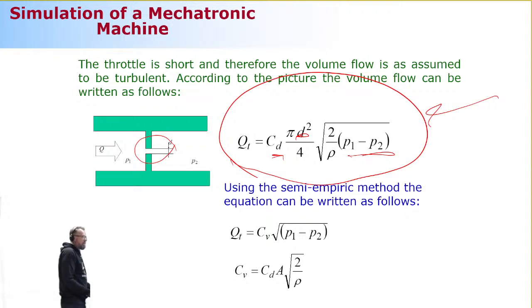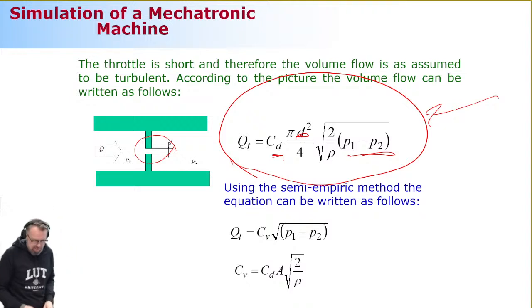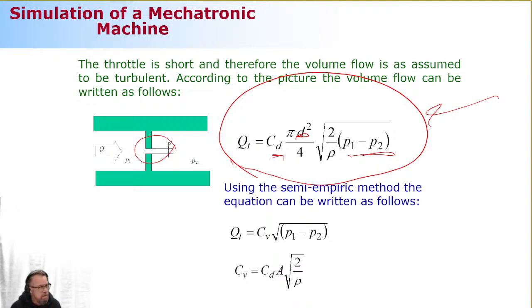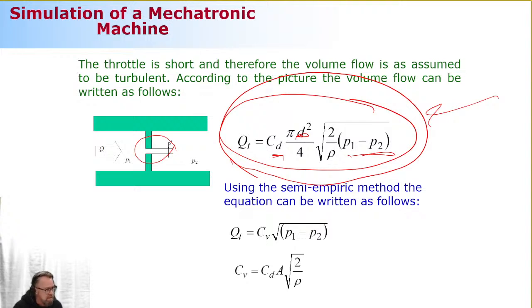it's difficult. It's difficult because most of the components you use in hydraulics are way more complicated than a throttle valve. Just to give you an example, a pressure relief valve has a spool that is moving because of several different forces. There's a flow force, there's the pressure imposed on the spool, there is a spring force, and so on and so forth. Creating the equation for the spool movement is going to be a painful task if you're planning to do that in detail based on physics. Possible, but very complicated.